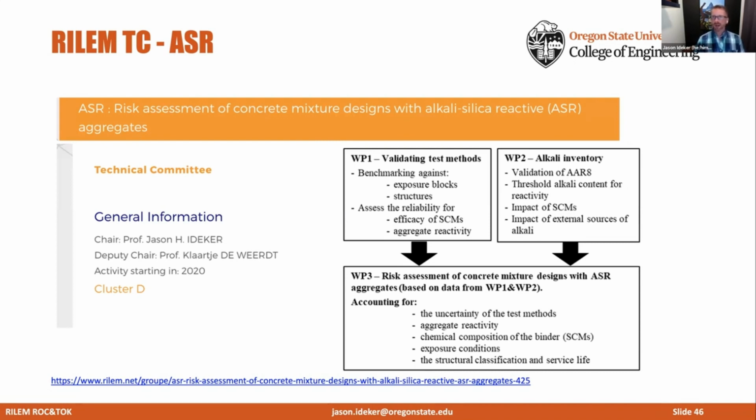We have 3 different work packages. Work package 1 is looking at validating existing test methods, right in line with some of the things we talked about today. Work package 2 is looking at alkali inventory and validating that new RILEM test method I mentioned, AAR8. And all of this is going to feed into work package 3, which is a framework for risk assessment of concrete mixtures with ASR susceptible aggregates. So I really encourage you to check these out.